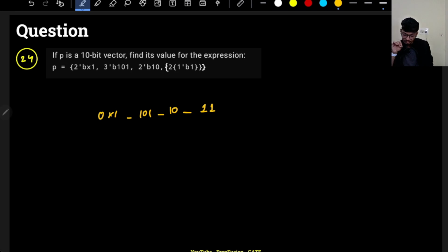Now people will get confused that this is a hex number, but this is not a hex number. To emphasize that, I will write here 10 tick b, 10'b, to emphasize this is not a hex number. Now people will understand this thing. This is a 10-bit number.